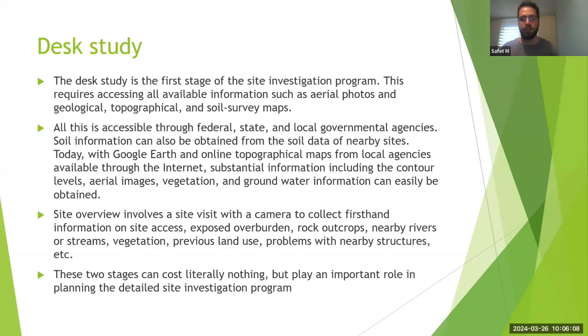You need to pay for it a little bit, but it's a lot easier to plan actual geotechnical investigations if something is available. Today, with all the online tools, such as Google Earth, you can find topographical maps on the internet. You can find digital elevation maps, lidar scans, and elevation maps. You can find a lot of hazard maps regarding landslides or the risk of landslides, the vegetation, and even the groundwater, depending where you are.